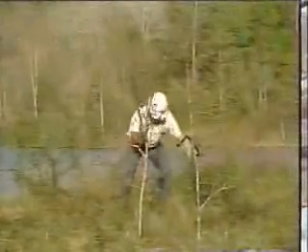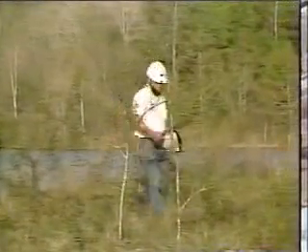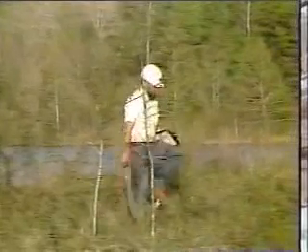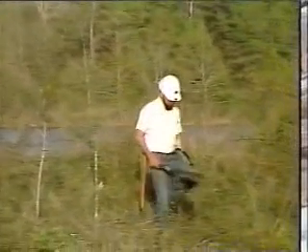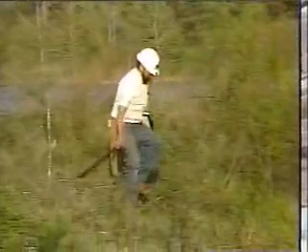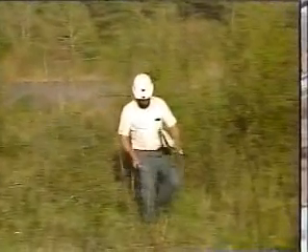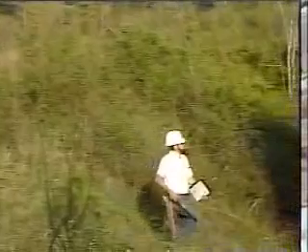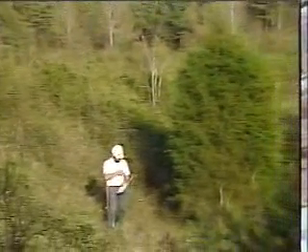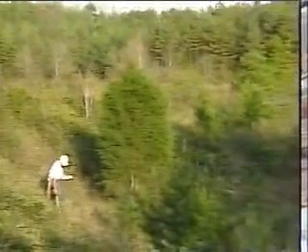Let's move to inappropriate vegetative growth. As valuable as a healthy shallow root system is in preventing erosion, there can be too much of a good thing. There are two categories of inappropriate growth: excessive growth and deep-rooted vegetation. When excessive growth is present, problems threatening the dam can develop and yet remain undetected, a very dangerous situation.